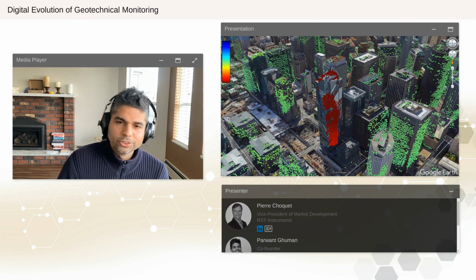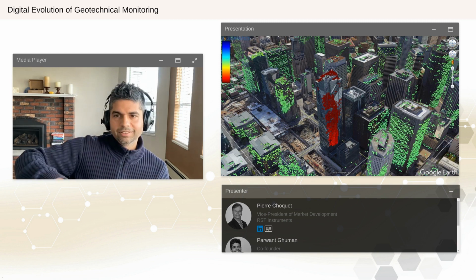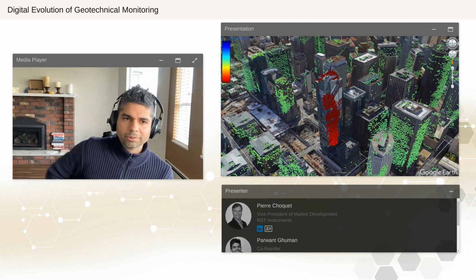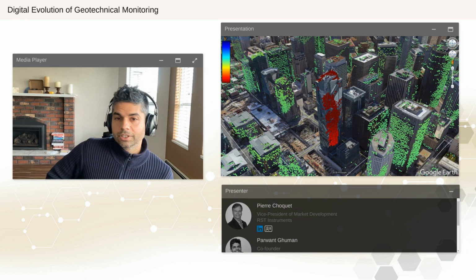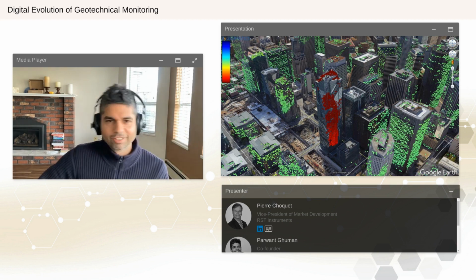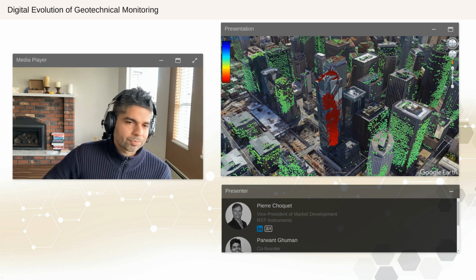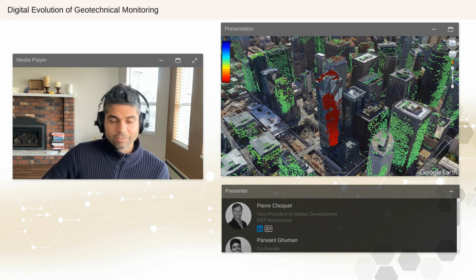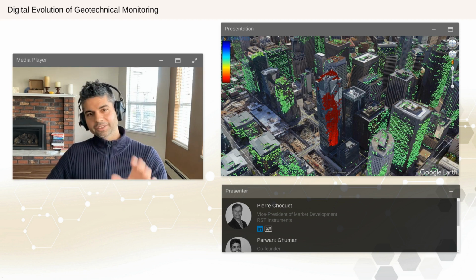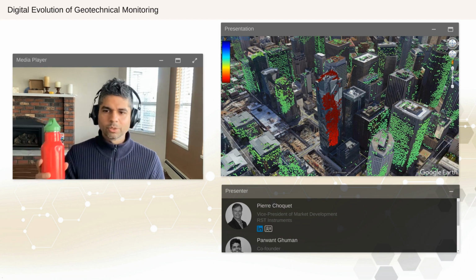You have thousands of points, or hundreds of thousands, millions of points actually. But these points are nicely overlaid on all these towers in 3D. And there's tons of points on each building. And the Millennium Tower, which is the building in the center, sticks out really like a red flag here. So right away, we knew something very unique is going on with this tower. And we had about 1,200 measurements on this building. And we decided to do some analysis on it that was fairly unique and unprecedented for InSAR. We basically took these 1,200 points.